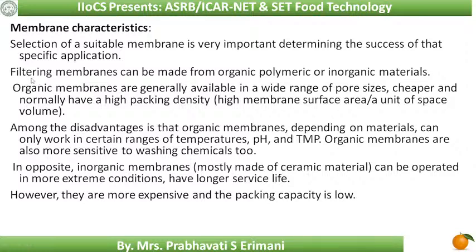The filtering membrane can be made from organic, polymeric or inorganic material. Organic membranes are generally available in a wide range based on pore size, and they are also cheaper, and normally have high packing density, that is, high membrane surface area per unit space volume.